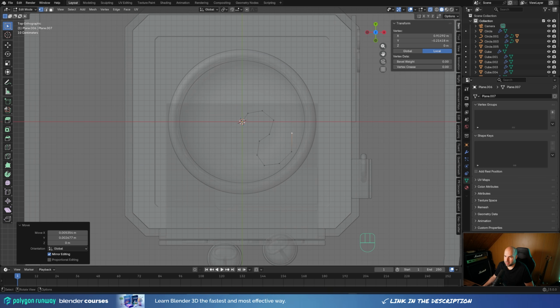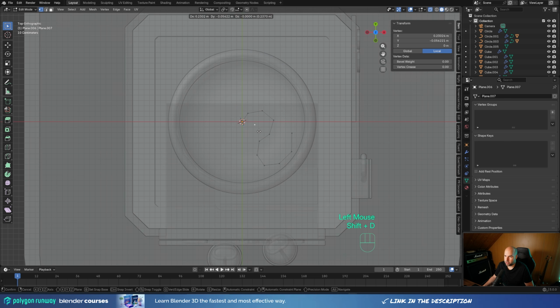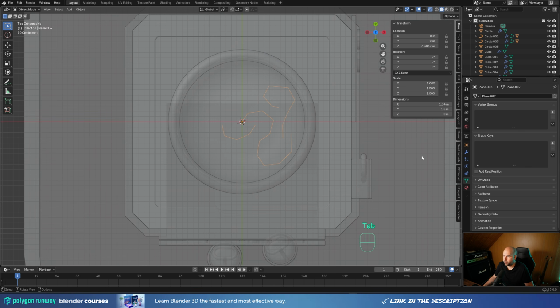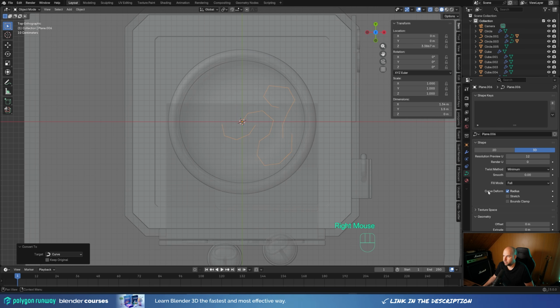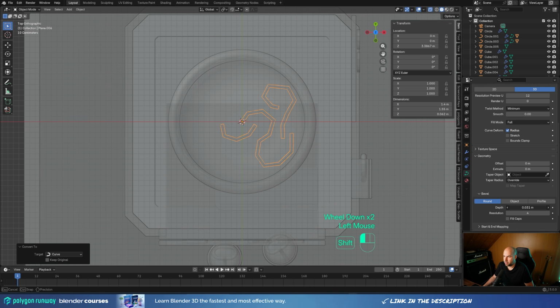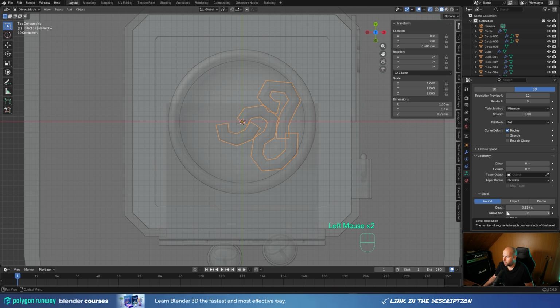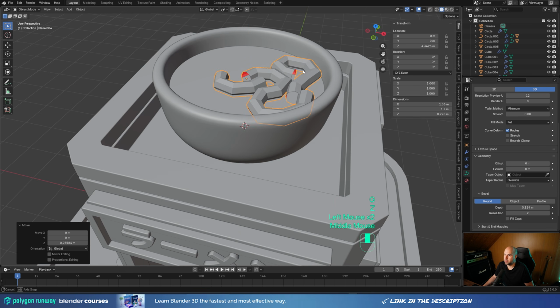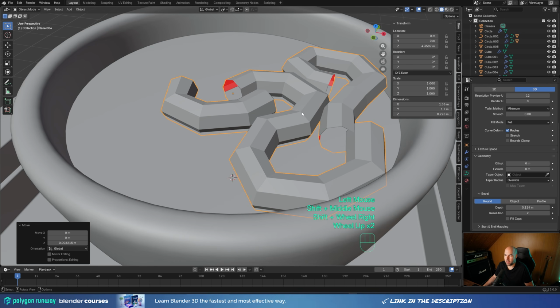It doesn't need to be dense, so let's select the first one again, press Shift D to duplicate and do something like this. And now here let's duplicate this one. Okay, and now we can tab out, right click and convert to curve, and again we'll add some thickness like this and reduce the resolution to 2. Let's press G then Z, bring it up, and let's disable the X-ray view so we see where it sits like this. And we'll need to close the caps here.